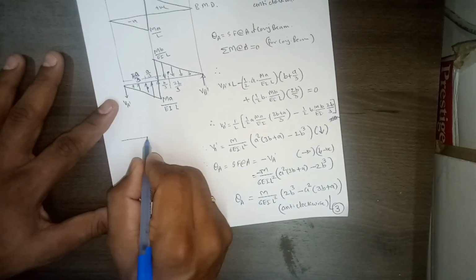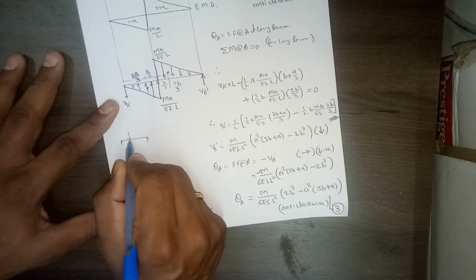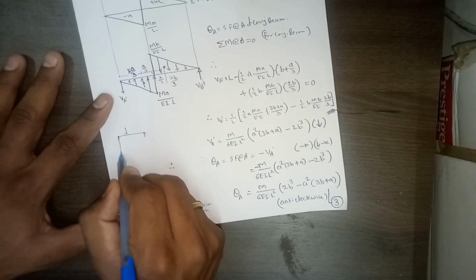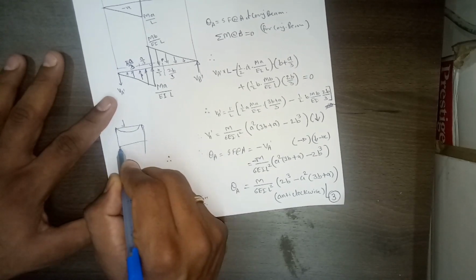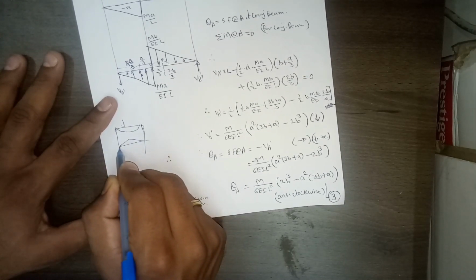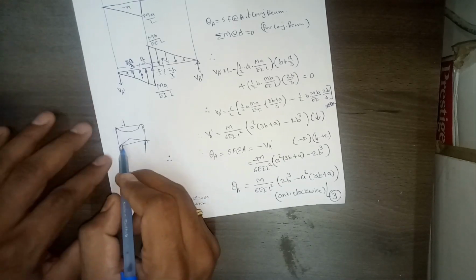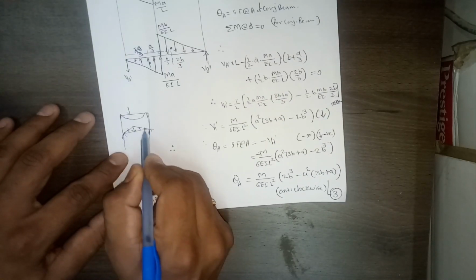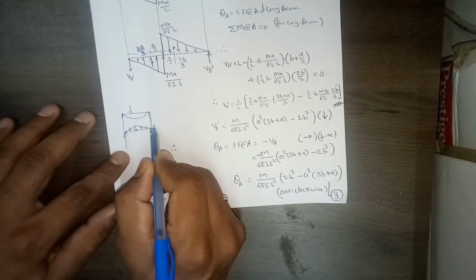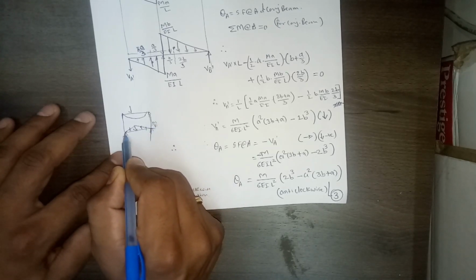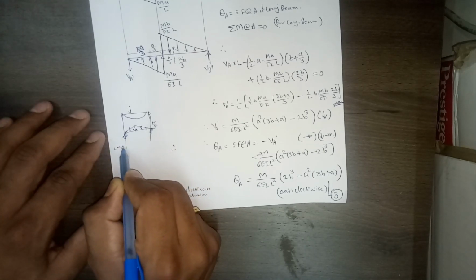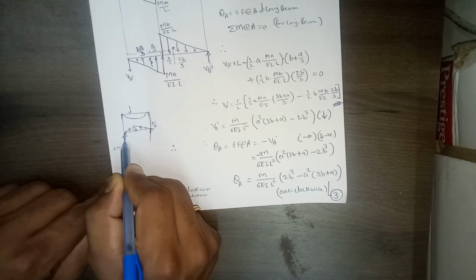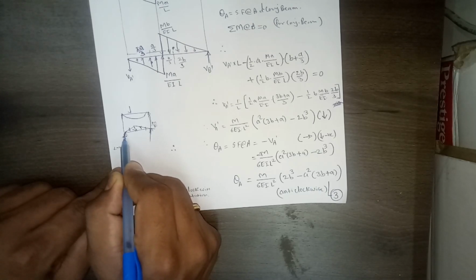So if you remember, for a normal problem, if we have this load, then this beam will rotate like this, right? If you try to plot the bending moment diagram, it will look like this. Here, you understand, this is the conjugate beam of this problem, this is the M by EI load, and this reaction is upward. So the shear force here is positive, because when we calculate left to right, upward force we assume positive. So what does this positive force indicate?